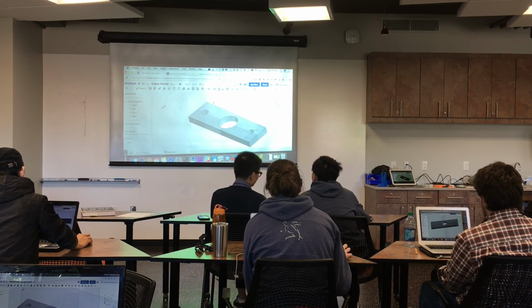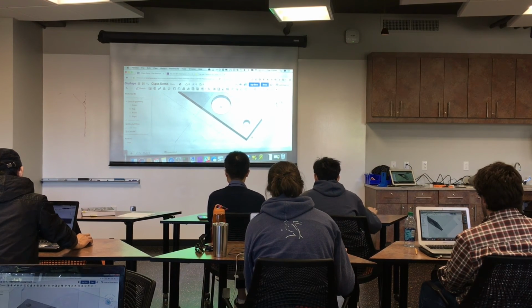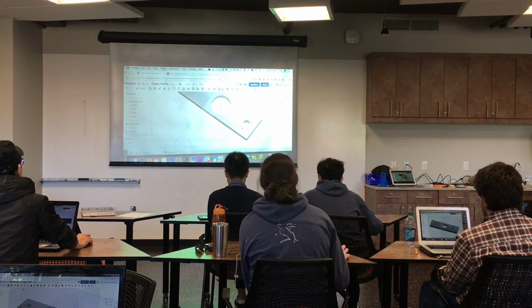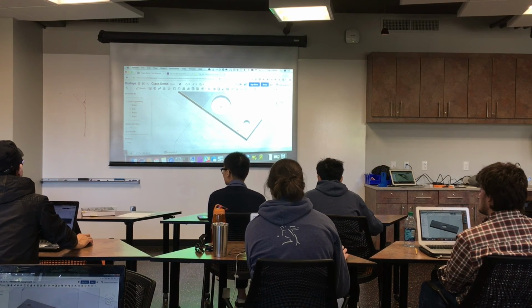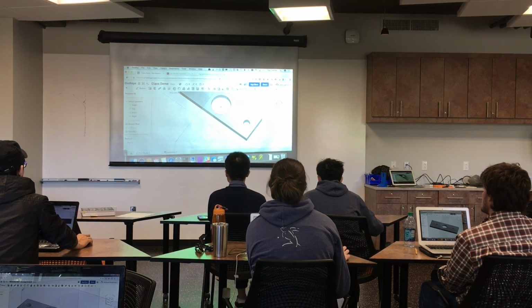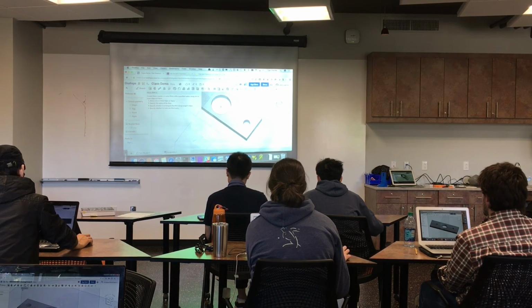What we need to do is, remember I had nice rounded corners on that one in the picture. Why not? It's a 3D print. We can make it as nice as we want. So up here, now that we're in the 3D view, go to the fillet tool, which is just to the right. This is loft, and then thicken, and then fillet. And click fillet.